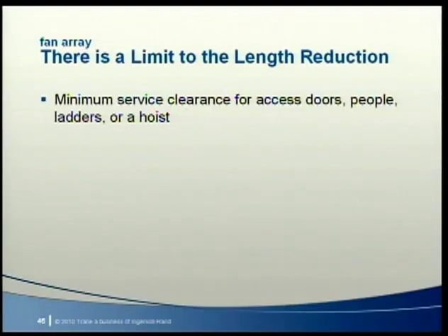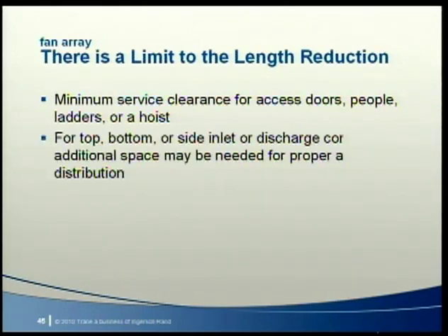However, there is a bottom threshold to this length reduction. First, there is a certain amount of space needed upstream or downstream to allow the fans to be serviced or replaced, if necessary. This includes space for a person and for a fan motor and/or wheel when the fans are stacked in multiple levels. It may also require space for a ladder and possibly a mechanical hoist. Next, for applications where an inlet or discharge connection is made to the top, bottom, or side of the fan section itself, additional space may be required to properly load or unload all fans in the array.